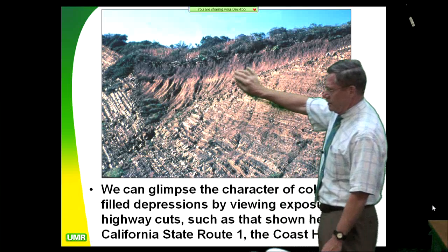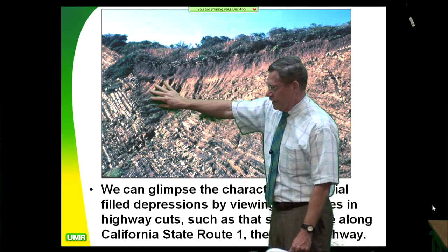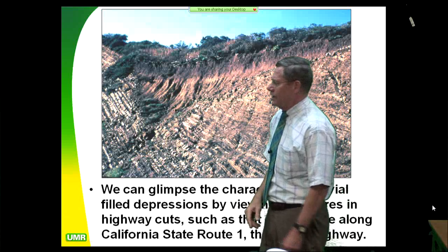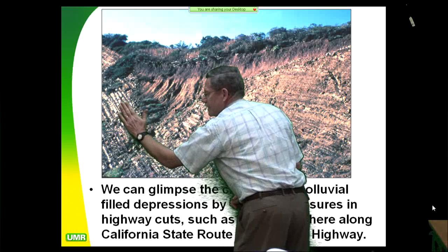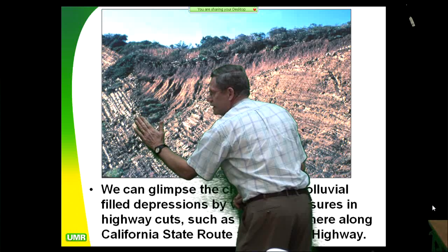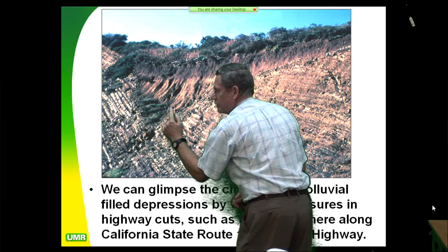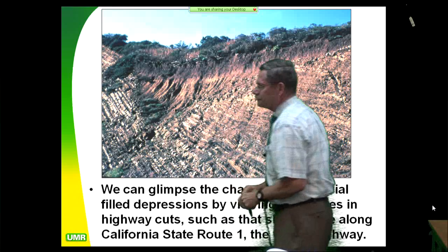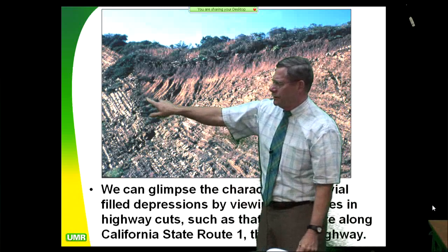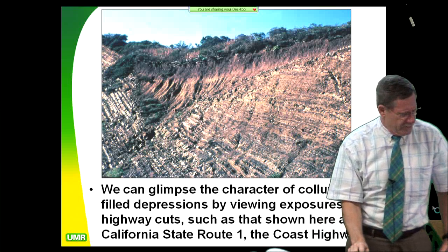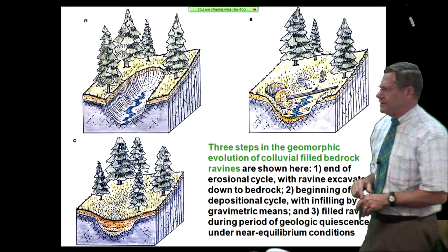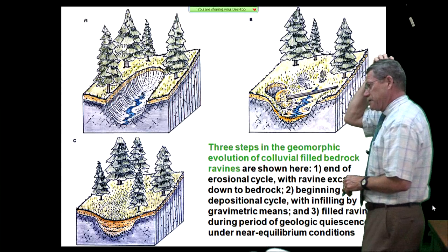This is just loose, loosey-goosey fill, natural fill, not man-made fill. And you've got this Miocene age and older bedrock down here, Eocene age. And so you have a permeability contrast here. So that's where you would need to put a subdrain if you really wanted this slope to survive in the long term. So if we look at cartoons, this is kind of the picture we have.